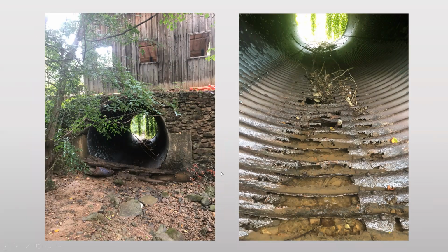Here we've got an example of a 138-inch round corrugated metal pipe culvert that is 51 feet in length, and it was located here in Birmingham, Alabama. And you can see from the close-up picture here, again, this culvert has experienced severe abrasion and corrosion to the bottom invert of the pipe. And we can also see a lot of common materials, being rock and wood or branches that are carried through the stream, have gotten lodged in these voids.